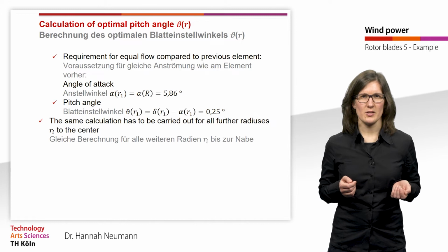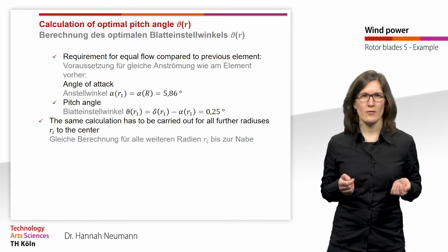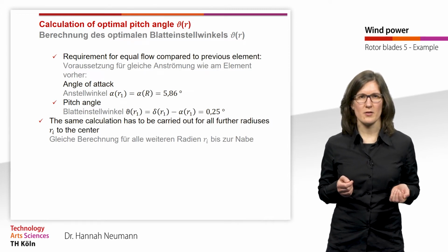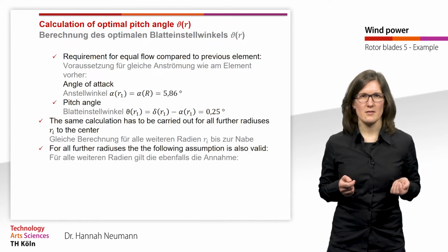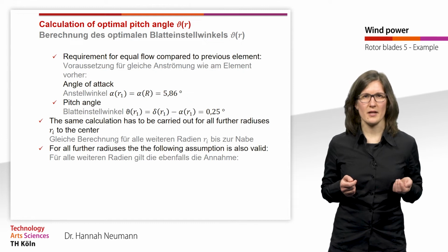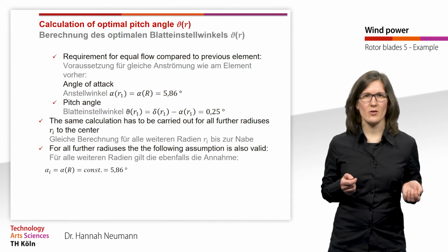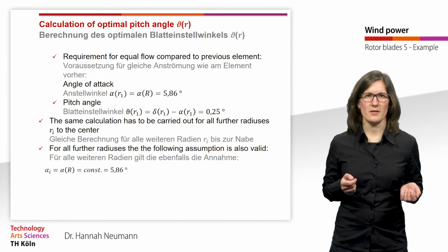The same calculation has to be carried out for all further elements to the center of the rotor blade. For all further elements, the assumption that the angle of attack alpha is the same at all blade elements has to be valid.